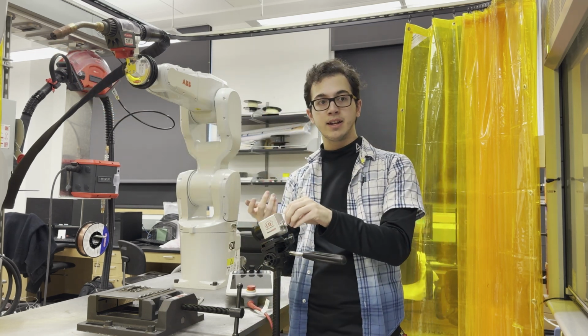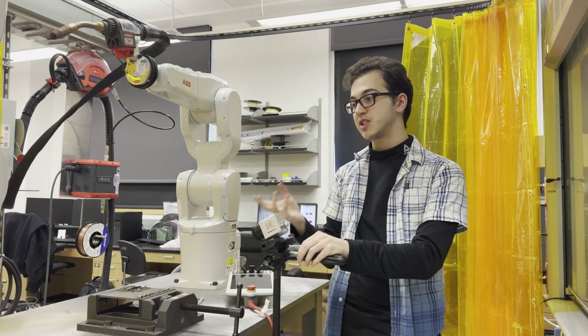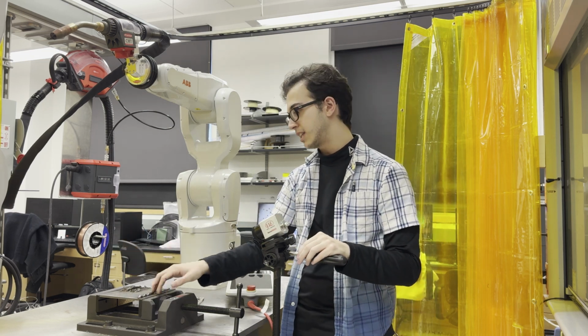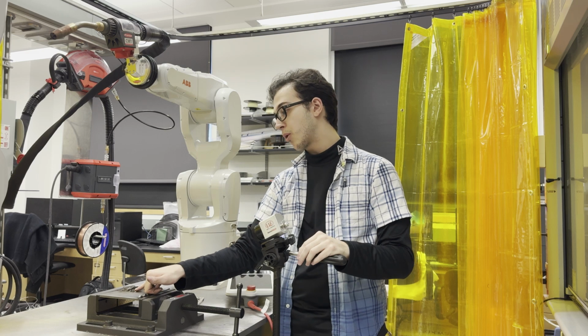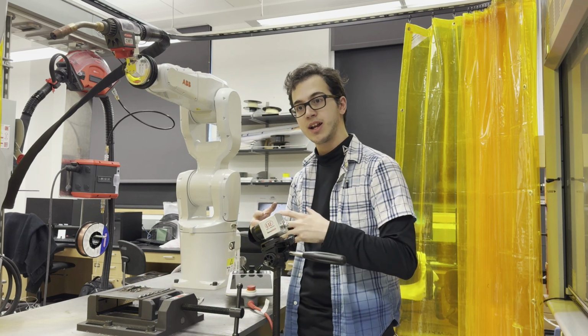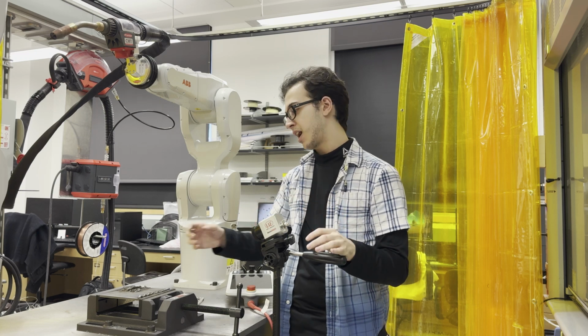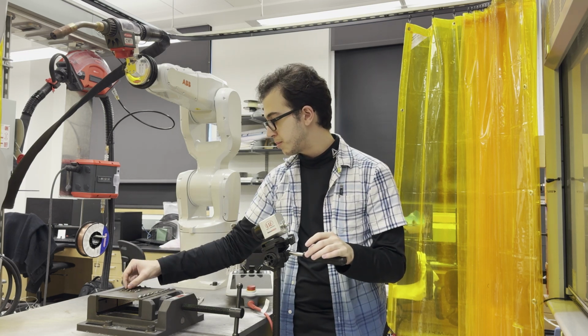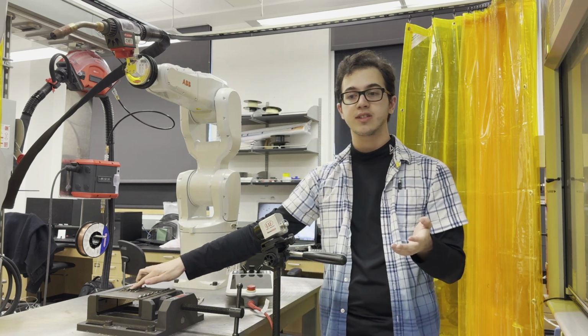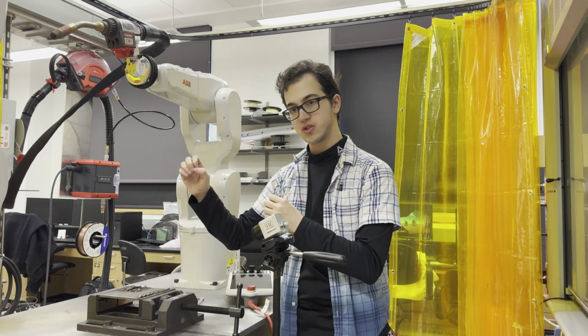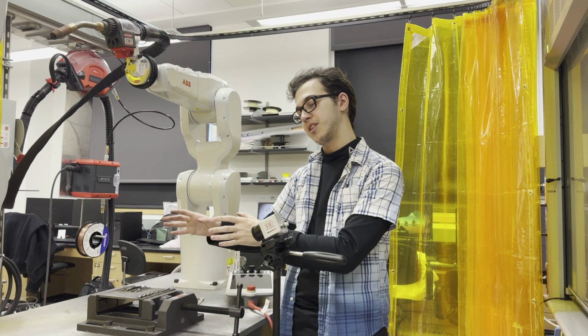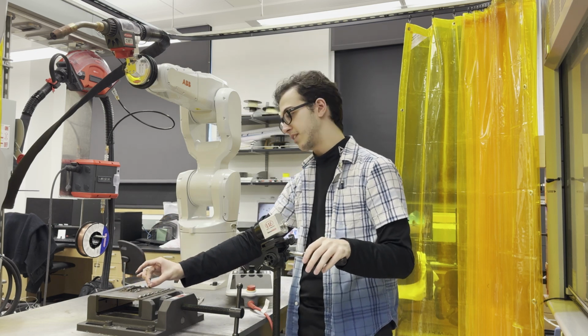Whereas in an abnormal weld, you would see a lot of spattering, some uneven heating, and that results in these porous welds that you see where gases are trying to escape out of the molten metal, and they leave behind these large pockets. And also you see large depositions at the initial stages where the arc has just struck and it suddenly deposits a large amount of material instead of moving steadily.